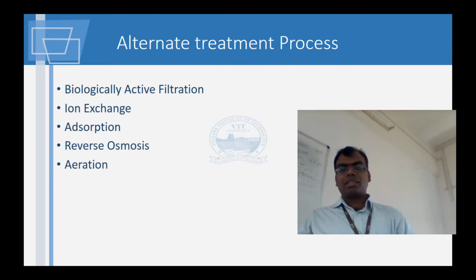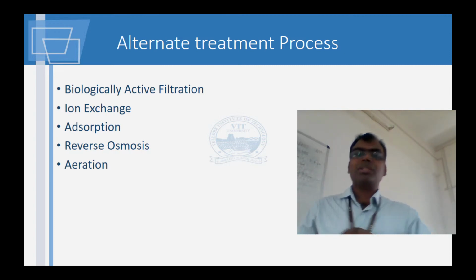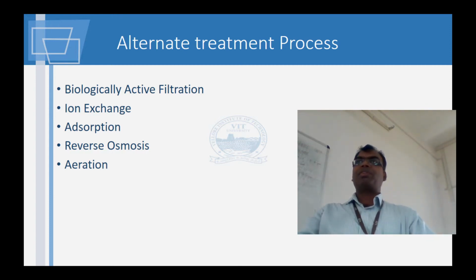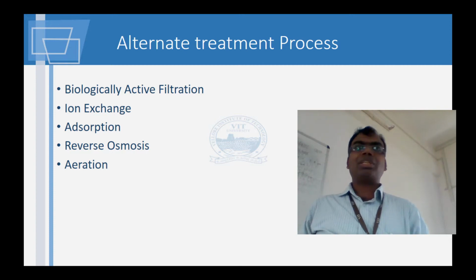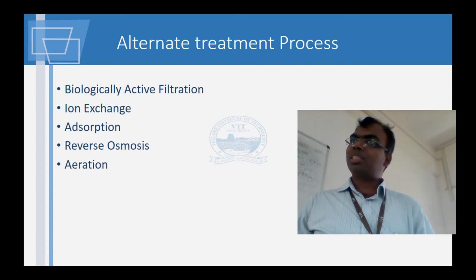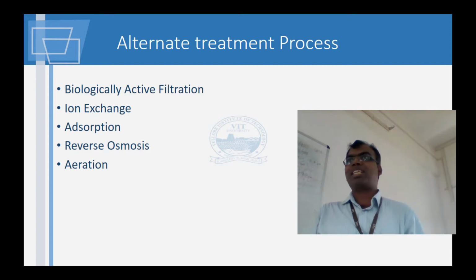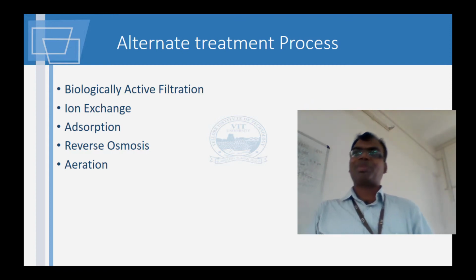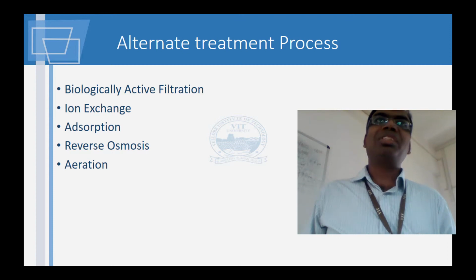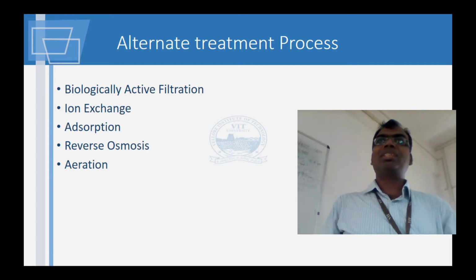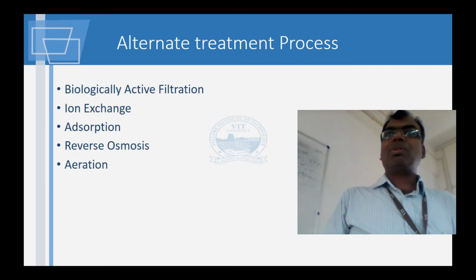Okay. Next is aeration. What is aeration? It is nothing but adding air. Please remember in one of the videos you saw that water is falling like a fountain. That is the simplest way to aerate. You can use something like a Parshall flume, or whatever we talked about. Except for the hydraulic jump, I don't think that might be a very appropriate thing. But you just need violent agitation to let atmospheric air into the system. So that is one thing.